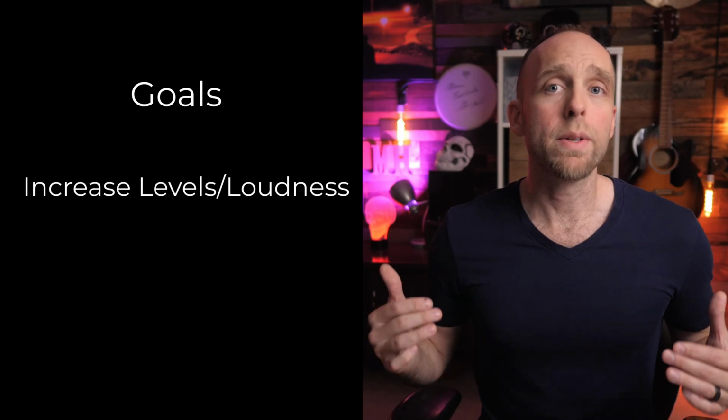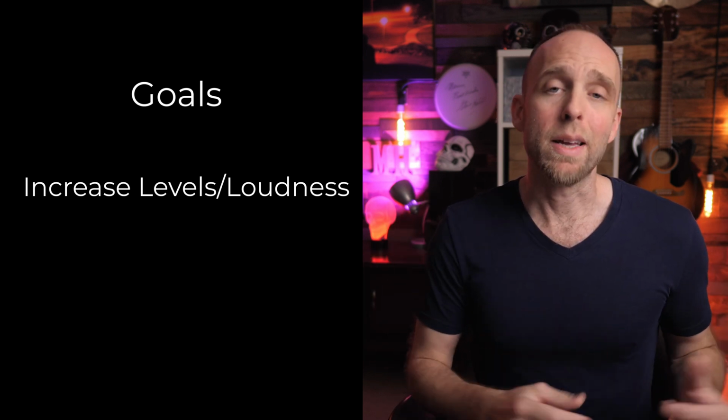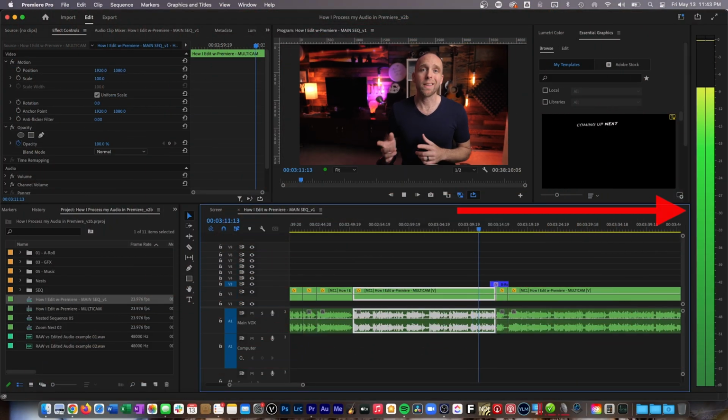And lastly, I have two goals in mind when processing my audio. Number one, get the overall loudness of the audio up to a level that can compete with other content on the internet. And number two, to have that audio sound as clean as possible. Now, to ensure your audio levels are loud enough, I do two things. Number one, I always make sure I can see my meters in Adobe Premiere Pro, and I have my meters docked and locked on the far right side of my Premiere window.